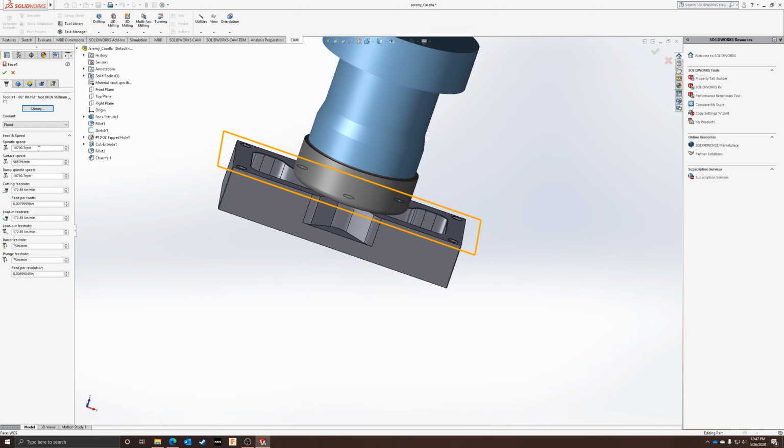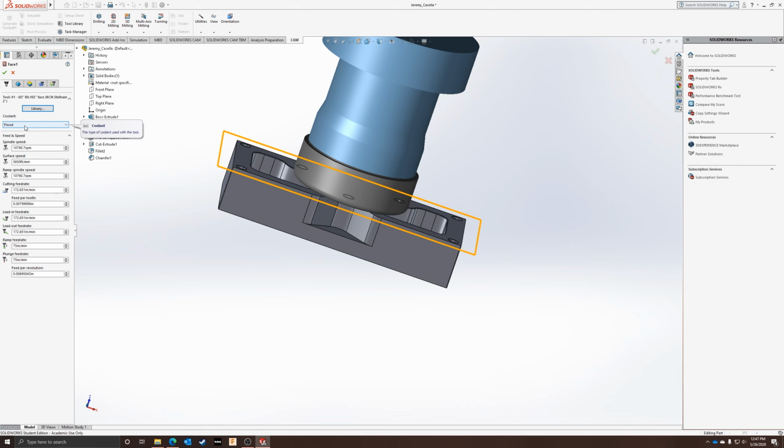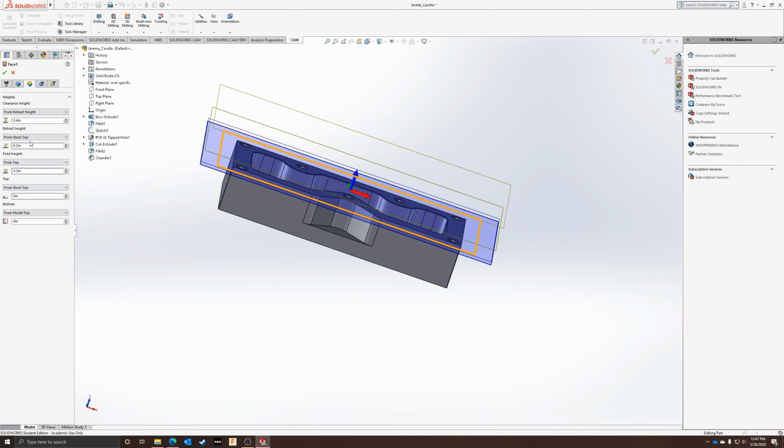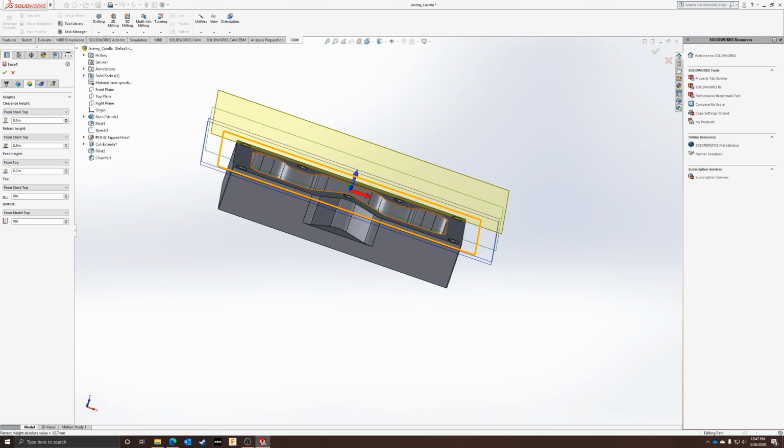So next thing is these feeds and speeds. This is already given to you, and it's perfect. It's from Bechtel's tool library, so ignore it. If you're using a machine with coolant that shoots through the tool, we'll select through tool, but for now we're really just doing flood, and that's a case-by-case basis. We don't need to select stock contours. A facing operation automatically selects the closest surface to face down to. You don't need to change anything here except for these two heights, which say 0.5 inches from stock top for both. What this does is it tells it where to move to each time it changes a position. So if I have multiple depths or I'm cutting and I'm going to different places, I need to reposition safely, so it'll go up half an inch so it doesn't hit anything. That is your heights bar.